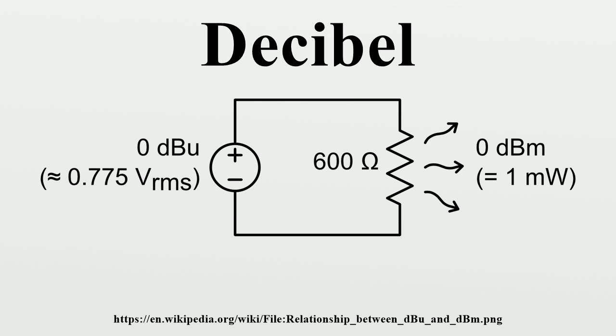The decibel symbol is often qualified with a suffix that indicates the reference quantity that has been used or some other property of the quantity being measured. For example, dBm indicates a reference power of 1 milliwatt, while dBu is referenced to approximately 0.775 volts RMS. In the International System of Quantities, the decibel is defined as a unit of measurement for quantities of type level or level difference, which are defined as the logarithm of the ratio of power or field type quantities.